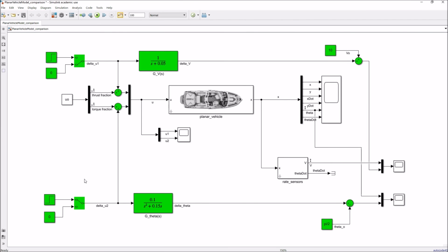So that's great. I think what this shows is both of these systems seem to work well. These two linearizations that the linear analysis tool computed for us work very well. Again, be a little bit cautious here, because this system was simple enough that there was no cross-coupling, in the sense that GV and G theta at this operating point, linearly, are not coupled. But we know that they definitely are coupled in some sense.